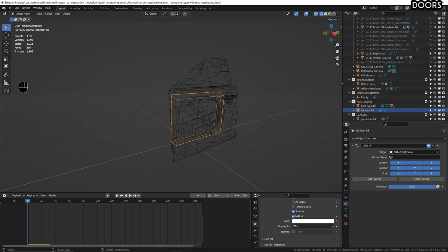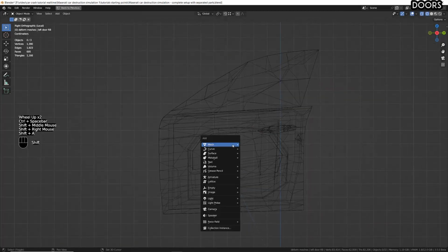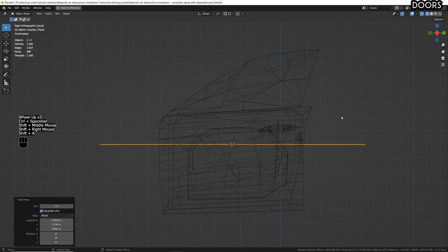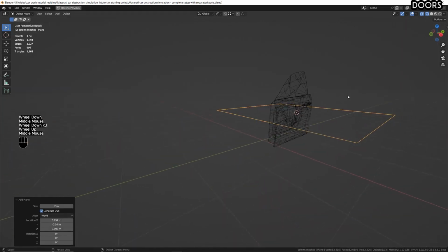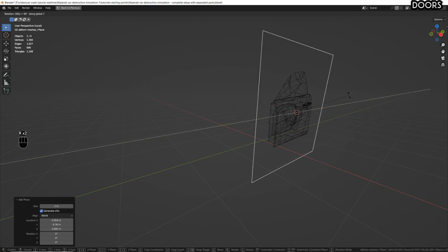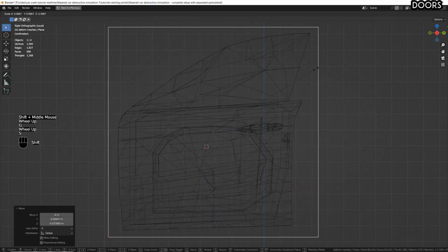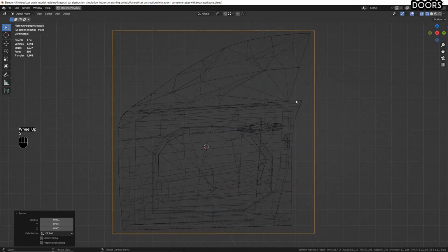By the way, okay, let's make the deform mesh. So I'm going to select the deform meshes collection. From the side view, I'm going to create simply a mesh plane, flat like this, and I'm going to rotate it by 90 degrees. So press on the keyboard R, Y, 90, and then press enter, and this should be perfectly straight. Yes. Now the deform mesh should actually cover entirely this door, including the glasses, even if the glasses is a separated geometry, because I also want the glass to follow the deformation before breaking.